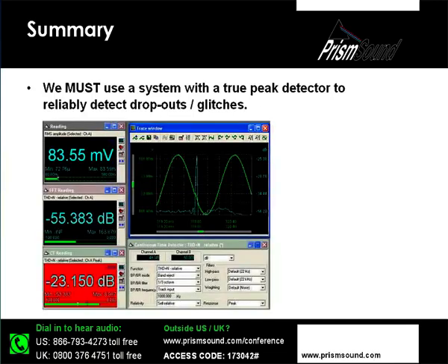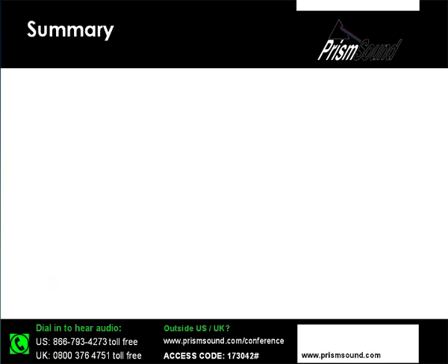And we saw earlier that the various methods that we talked about, whether it's looking at an oscilloscope trace, listening to the signal, measuring its amplitude, measuring its RMS THD plus N, all of these methods potentially have their flaws, and it is the true peak oversampled and interpolated measurement function of, in this case, the D-Scope, that is the tool to use in conjunction with our unique event manager features, which allow you to automatically detect any limit breaches from, in this case, your THD plus N measurement.